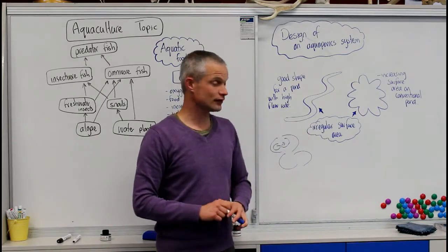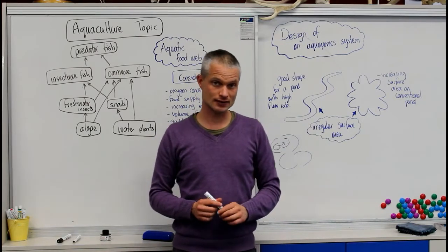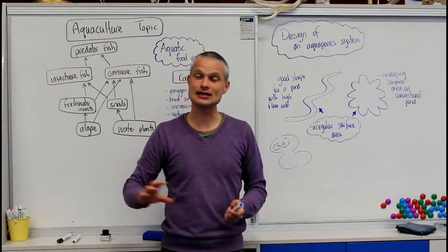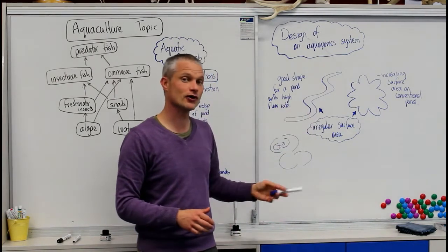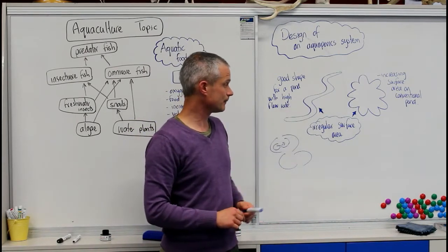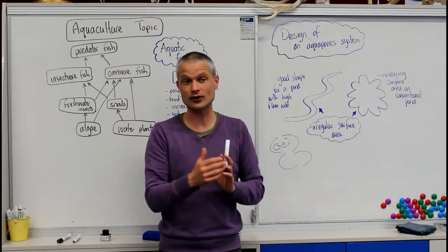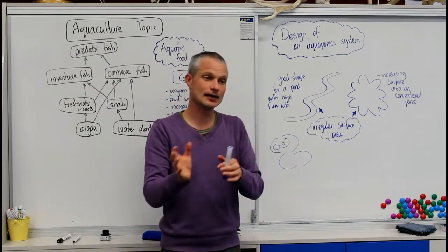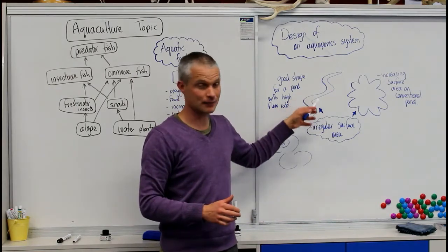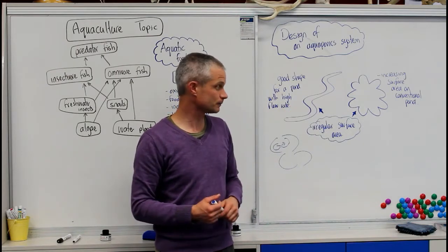Some of the shapes that can influence production, if it's quite a high flow rate through that water system, a more sigmoidal shape that imitates the natural bending shape of a river will help create a nice laminar flow of water through that system, so that there's not too much turbulence that can stress the fish. And also an increase in edge, instead of just a straight channel that the water goes through, the bending of the stream will help replicate the natural flowing form of a stream, create more habitat, create more surface area, create more edges on that system to increase production.